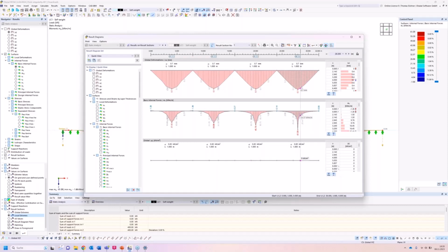In general, especially in reinforced concrete, you will put, let's say, 11 square centimeters per meter. Yes, so it's per meter. In reinforced concrete, forces mostly are able to redistribute because there are a lot of safety factors in the calculation and they don't come from nothing.